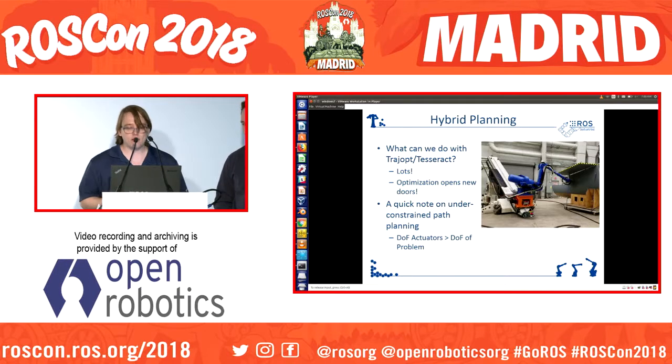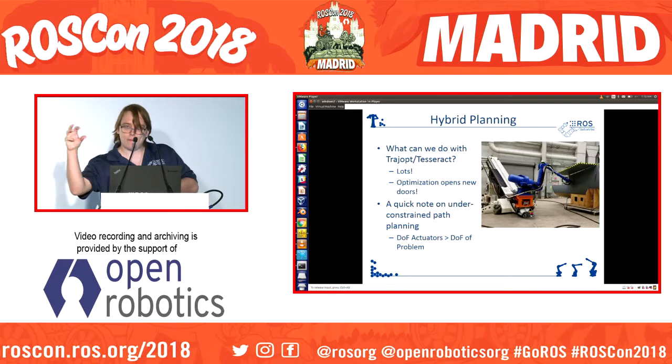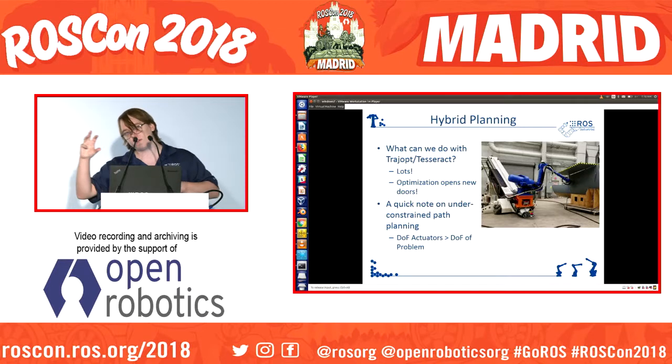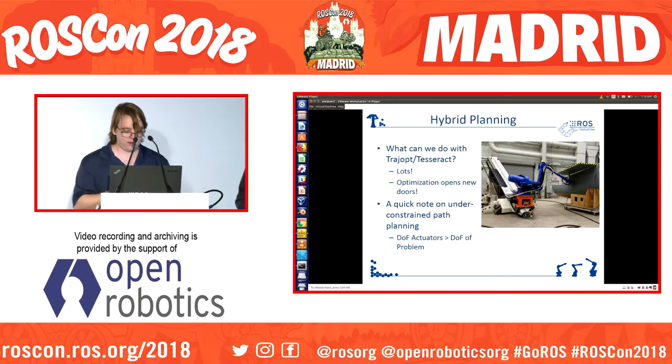If you have a rail like on this robot and it's really slow compared to the rest of the system, we can use the optimization to allow the robot to take up slop in a linear trajectory. Like you want to maintain a constant speed, and the rail accelerates really slowly. Well, the arm can shoot out in front, and then the rail can catch up. And it's a really awesome opportunity to solve more problems and make them more reasonable.